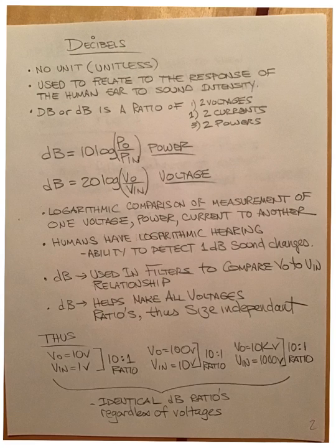Okay, so let's go off and talk a little bit about decibels, otherwise cryptically written as dB. Decibels are important in filter theory. They have no unit, and that's because you have divided usually a voltage by another voltage, and volts are in the unit of volts and they cancel.